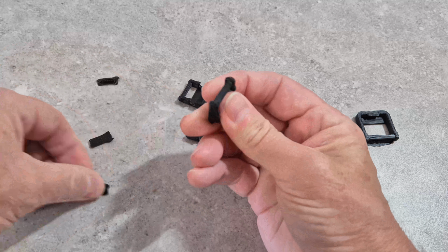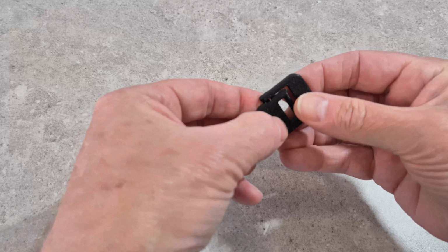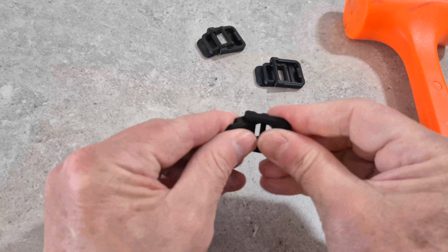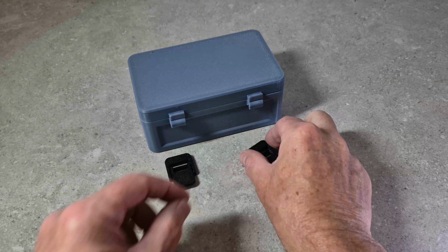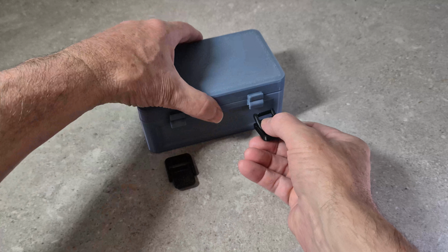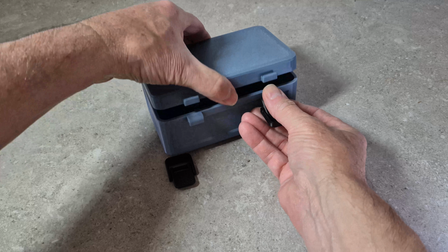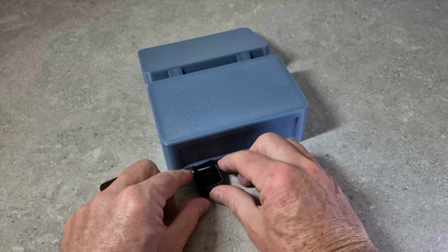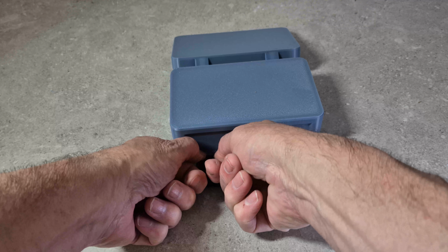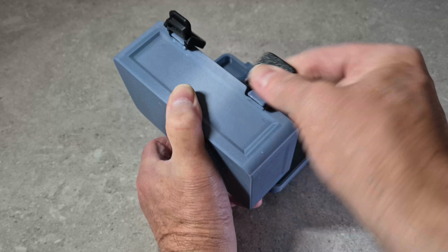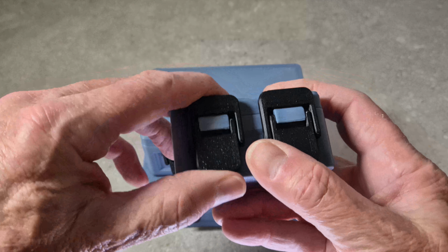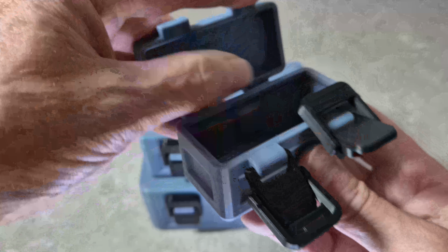Remove the tree supports and assemble them as shown here. If you've got a rubber mallet, give them a tap to assemble them. You don't have to smash them. Orientate the toggle latch onto the lower part of the case. Turn the case upside down so that the hinge tab is supported when inserting the toggle latches. Push the toggle latches into place. Rotate the toggle latches to ensure they freely rotate. You now have the ability to print a custom size case.